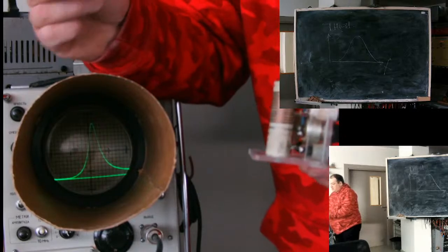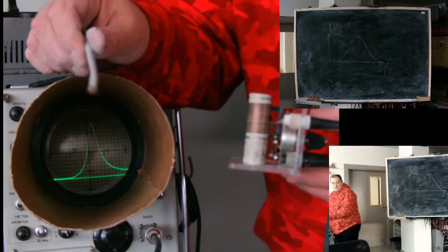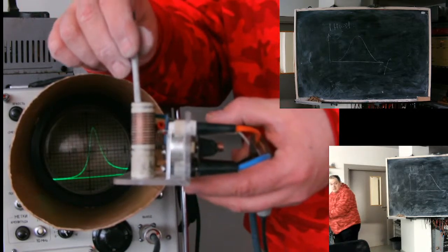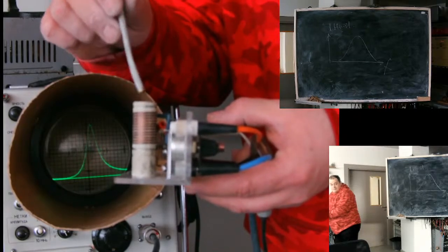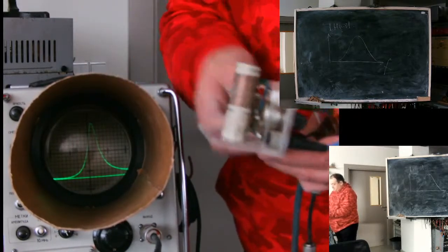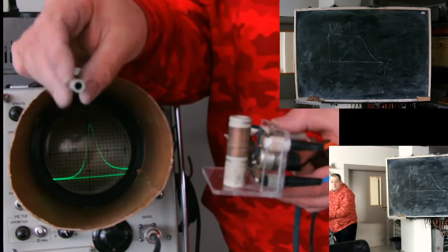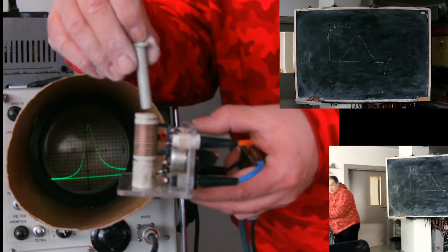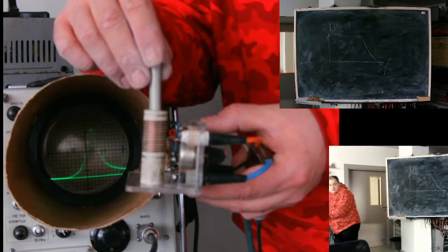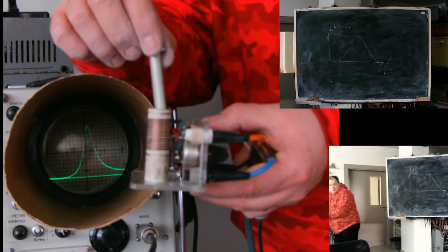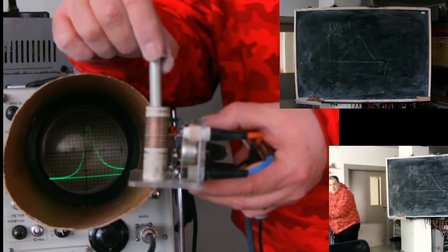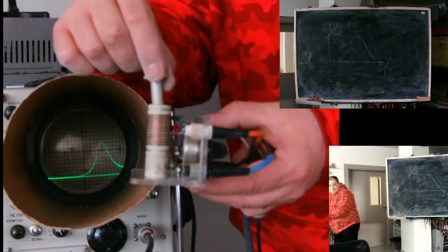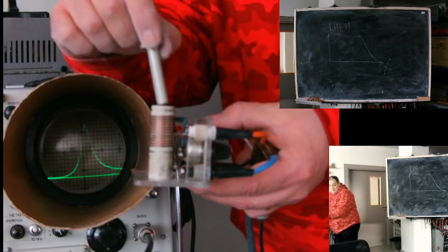On the opposite side, I have a brass screw. What will happen if I introduce a brass screw? It's a short circuit contact. It will increase frequency. To show the effect, this object, a small piece of aluminium pipe. It's a cylinder. It introduces a short circuit, kind of a secondary winding in the coil. You see what happens? Frequency increases because it absorbs magnetic energy. And of course, the losses will be high.